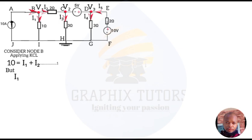But I1 is equal to the voltage from where I1 is coming from, which is V1, minus the voltage to where I1 is going to. Since there's no voltage, we say the voltage is 0, and V1 minus 0 is V1, all over the resistance between them. And the resistance between them is the 1 ohm that we have there, and V1 over 1 will still give us V1. So we have I1 equals V1. I'll term that my equation 2.